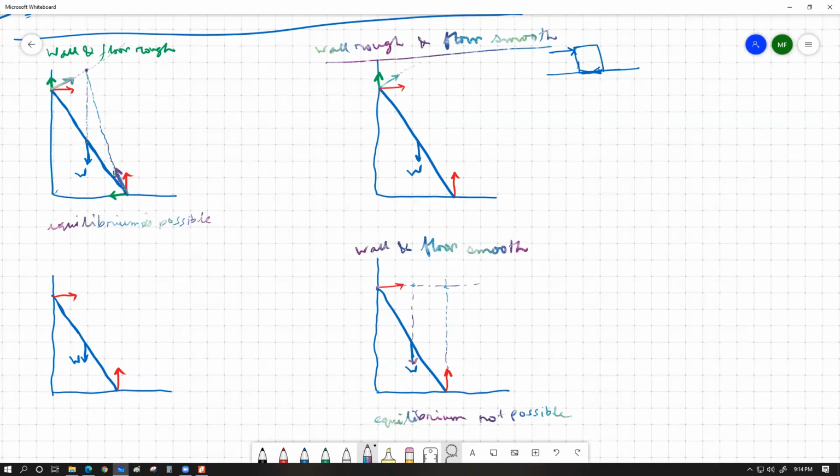Now, once again, if I extend this working line, and extend this working line and extend this working line as well, what you should find out that also in this case, these two forces cannot have a common cross point because they are perfectly parallel to each other. And also if you consider the common cross point of this resultant force from the top end with the weight or with the reaction force from the ground over here, we don't simply have a common cross point of all the three forces. If that is the case, we are going to say equilibrium not possible.